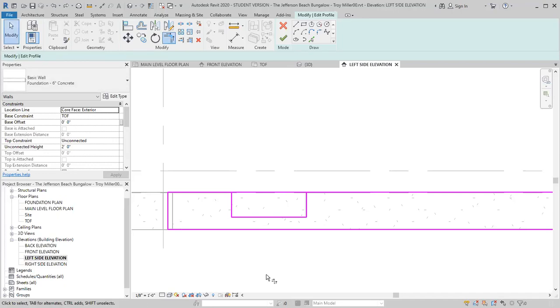So now what I'm going to do is just the opposite. I'm going to click here and I'm going to click on, whoops, I did a couple of undos and I lost my split. So let me split that again. Now I'm going to select on that side of the vertical line and then on that side, and you can see I make that nice, crisp, clean corner. I'm going to go ahead and do the same thing over here.